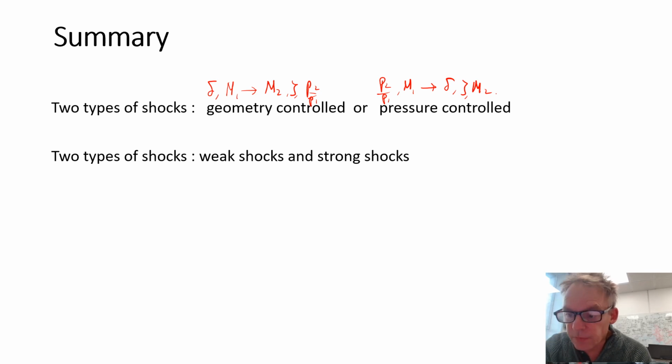These occur in two quite different problems. Pressure constrained ones we see in nozzles, outlet flows, and these types of things. Geometry constrained, we're usually talking about the inlets of a jet engine or the flow round lifting surfaces.